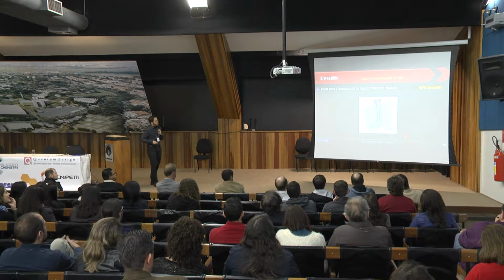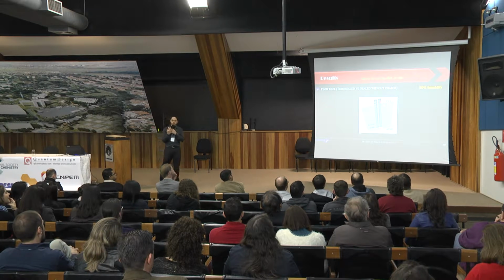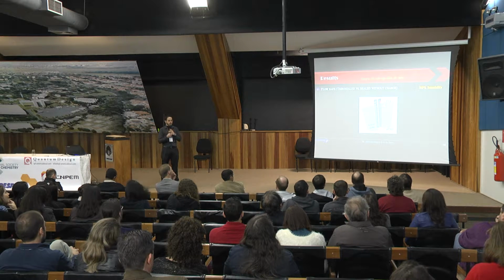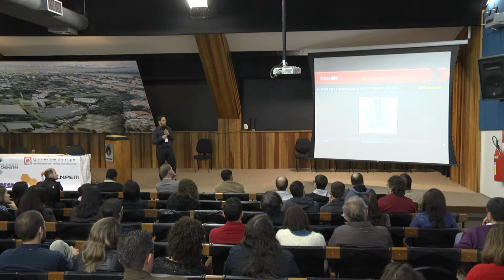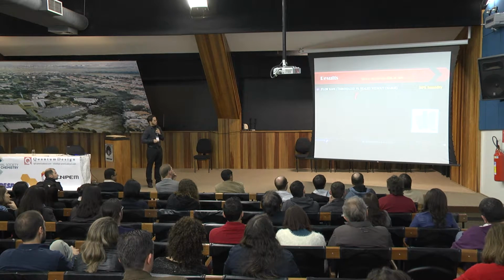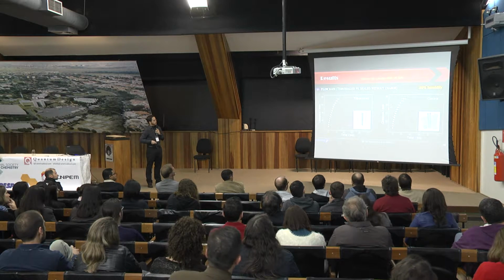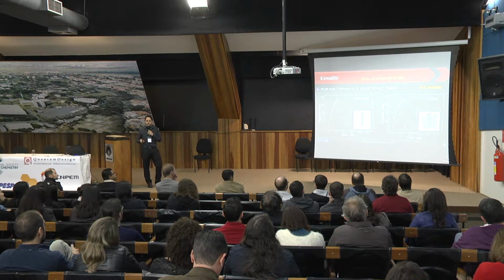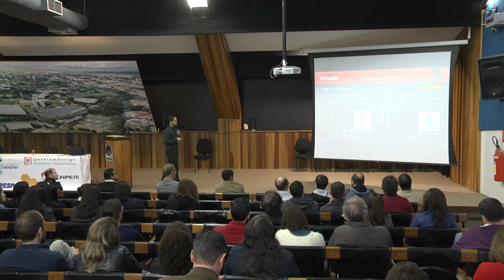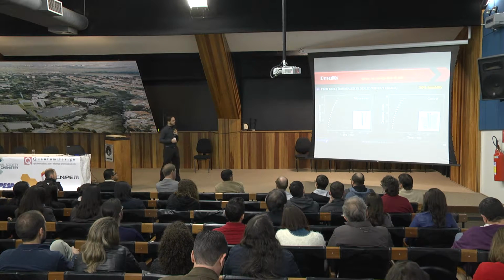To confirm that, we tried another experiment. This time, using PET closing both sides, but without charge. We put some glass slides to keep the PET flat on both sides of the channel. We did the same experiments, and as you can see, for the uncharged and the tribosealed device, we have the same behavior. So the charge has nothing to do with it. The charge was used just to seal the PET.